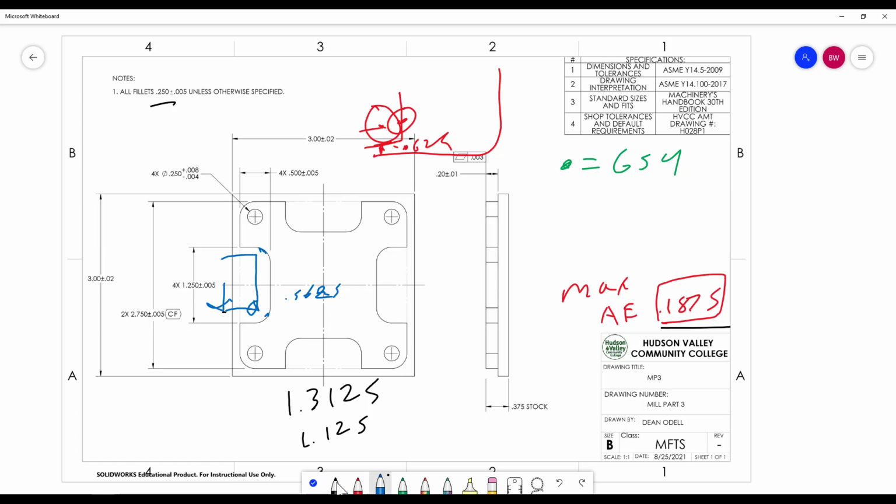This is not to scale, so unless you drew it to scale, you don't know. But we know that because the edge of the cutter will not go past this line, and a 1/16 away here, we know we're good because the arc has not started yet. So let's plug that inch and an eighth in.